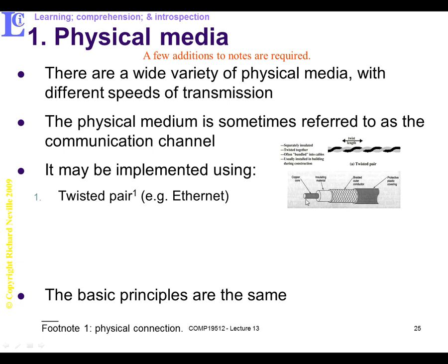Then we move on to the type of cable you might have seen in your old-fashioned analog TV. This type of cable is called a coaxial cable. So this is the live signal down the middle, and it's totally screened by this braid, this conductor, and in between them is an insulator, and then this braid is covered by another covering. So these are much more expensive than these, and they're also much more efficient because basically they're screened, so you won't get as much crosstalk as you would if you put twisted wire pairs together. Coaxial cable should give you hardly any crosstalk due to the way they're physically put together, where the inner is the transmission line, whereas with one of these, one will be the transmission line, the other will be earth. So this is the earth, the outside shielding, and this is the live transmission signal on this one.